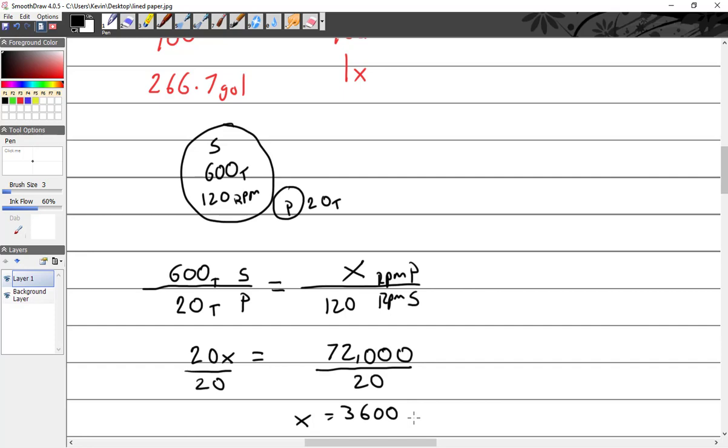I have a question. Since we're on gears, it was in the Q&A. It's about the speed ratios. The question asked, what is the speed ratio of an input gear with 36 teeth meshed with a gear with 20 teeth? It's 36 over 20. That's it? Yeah. I was overthinking it. So we can make it real simple. They're just asking for a ratio, so 36 over 20.